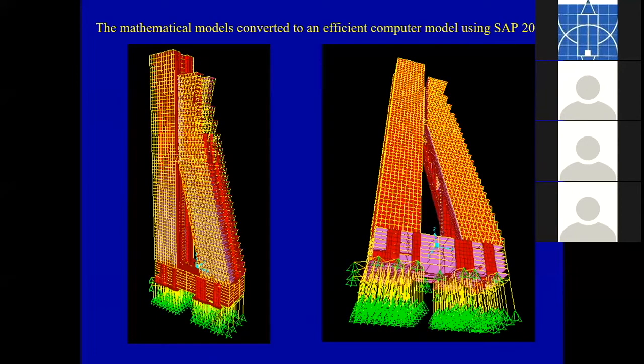And you can see this model of Altair that I made in 2012. And you can see in the model you get the superstructure above the transfer plate, here you get a transfer plate, then the substructure below the transfer plate, and then the foundation, the piles, all modelled, and a certain stiffness has been allocated to represent the bedrock stiffness. And the stiffness of the bedrock is very high, and we should learn how to give the spring stiffness to a model like this. So that's a part of theory that I will teach in due course.